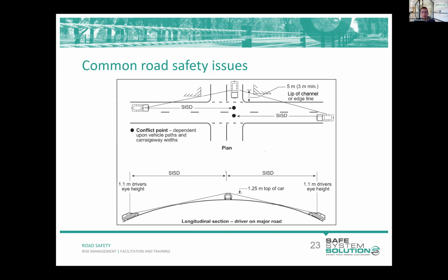Sometimes a plan set or a design report will include some information to demonstrate that sight distance requirements have been met. You can think about these types of things on site. You can do your own measurements on a plan set as well. But there are many: manoeuvre sight distance, crossing sight distance. And I suppose at the detailed design stage, it is important to have that awareness of the different design parameters, including sight distance, or have a person involved in the audit team that does.